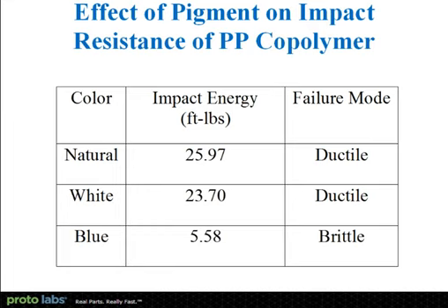And if you do a lot of work in polyethylene and polypropylene, and you do a lot of colors, you will have seen some of this, I'm quite sure. You also will have seen certain colors perhaps tend to produce a greater degree of warpage, or a greater degree of shrinkage. And this is all due to this interaction between the chemistry of the color system and the chemistry of the polymer.